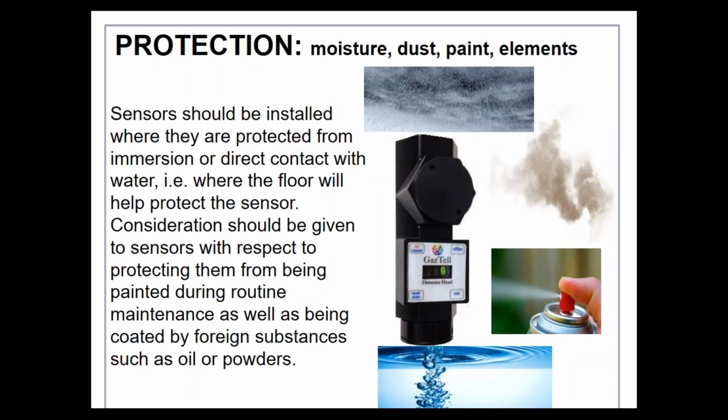Continuing to talk about the foam splash guard. You can see that there's dust, rain, water, ice, and aerosol sprays you have to be careful of. I've seen a lot of our sensors out in the field that are painted. Especially when a contractor comes in who has no idea what that device is, he just spray paints right over it, and then until the next calibration, nobody knows that they have no gas detection, because the gas detector is only as good as its capability of having gas diffuse across that flame arrestor. So that's almost common sense.